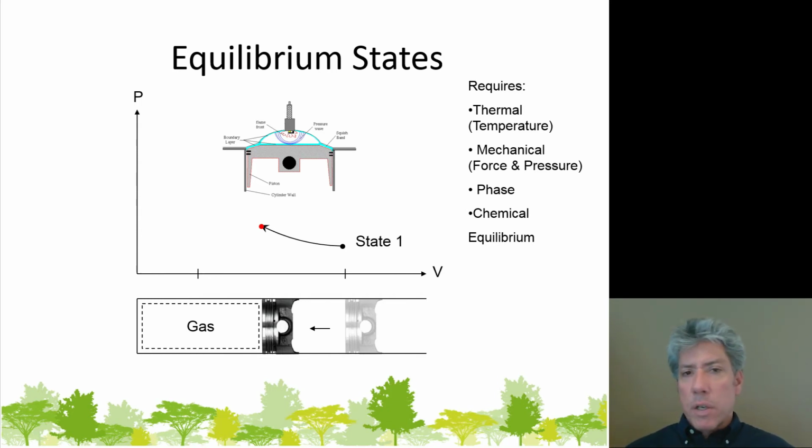Engines don't last very long with detonation. It turns out that in some high-performance cars you can end up with so much air and fuel that when you compress it too much, it gets so hot that the air and fuel just burns all at once without the spark plug starting the burn. And that is detonation. What they typically do is have a couple of sensors to detect detonation, then they'll retard the timing if necessary.